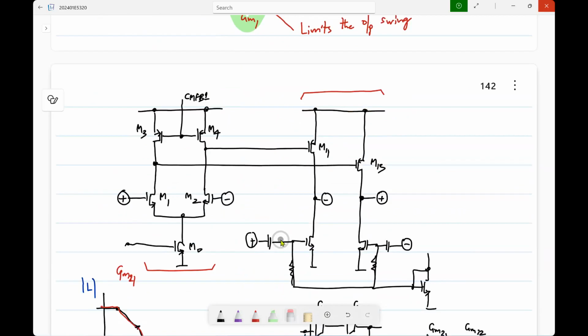So it's okay if you cut off some of the low frequency parts, because most of the low frequency loop gain is obtained by the cascade of these two stages. So as long as your AC coupling corner is such that the overall frequency response is not affected too much, you can use this one. Okay.